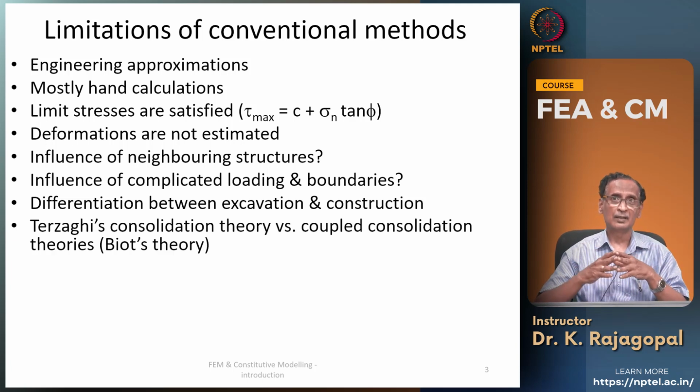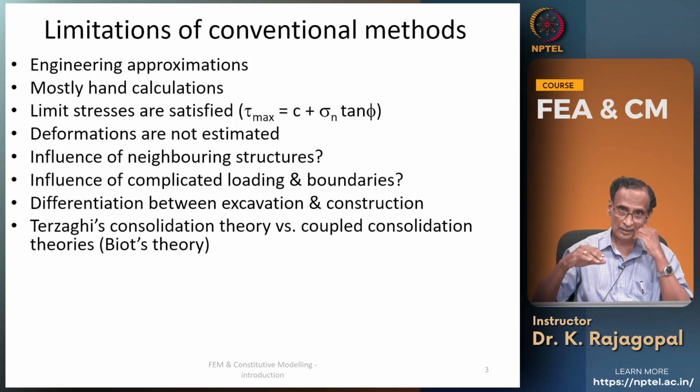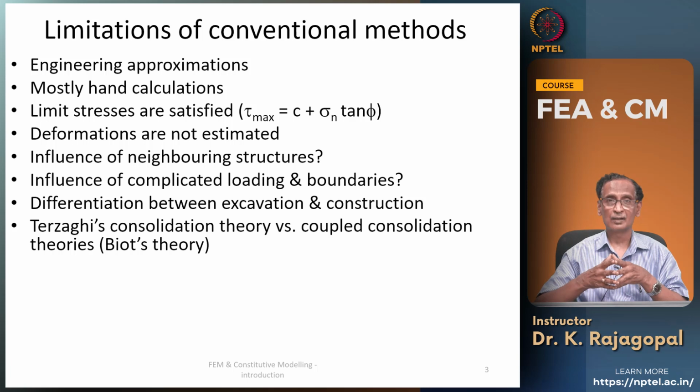And the other limitation that we have is our consolidation theory. Terzaghi's consolidation theory assumes that the total stress remains constant, the total stress being the pore pressure plus the effective stresses.